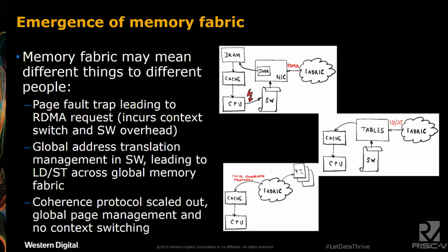What we mean by OmniExtend is basically going all the way, which means that your CPU on cache misses goes straight into the fabric. The fabric would carry your coherence traffic, right? So it includes your synchronization, and includes your memory consistency model that expands over the size of the entire memory. But now the idea is that this fabric would be something that anybody can buy and extend and scale up.